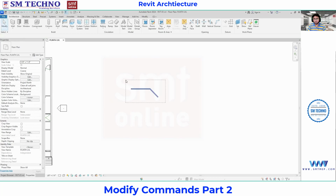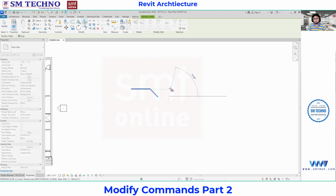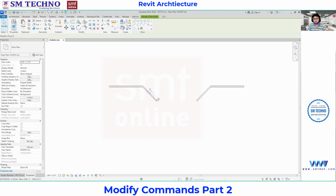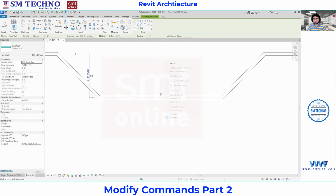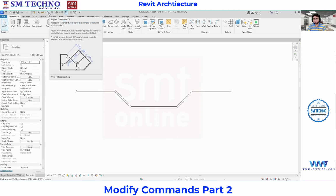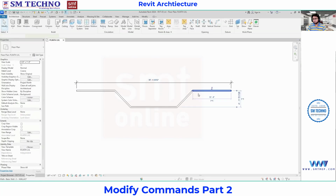I'll again mirror this object. In between, again, I'll draw a wall as a mediator. So now we have this object. What is the overall distance we have for this object? You can see in the quick access toolbar, we have a detailed class for dimensions, but for the time being, you can go with the quick access toolbar for a dimension. I'm selecting this point and this point. How much are we getting? Something like 48 feet.